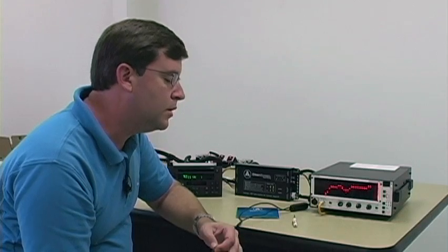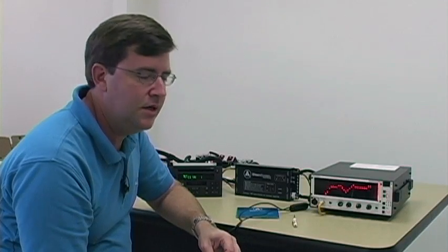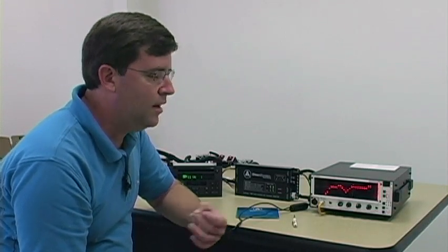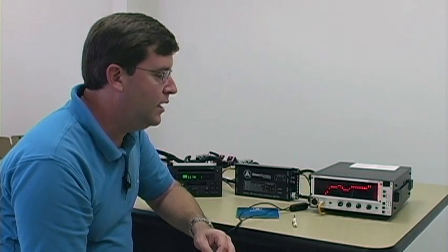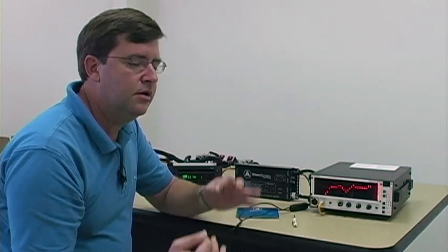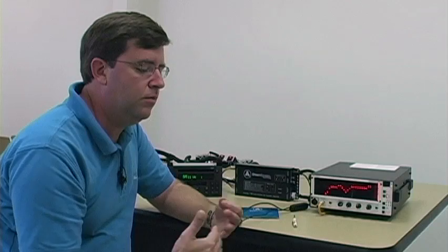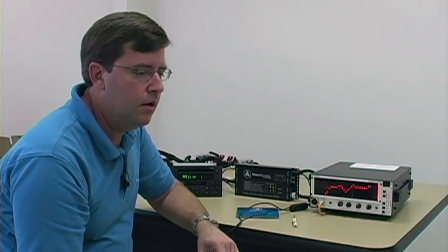There are several ways to do summing of signals. Probably the crudest way to do it is with line output converters, which we commonly refer to as LOCs. LOCs are passive devices that use little transformers, and they're inherently lossy by design, and they degrade frequency response further. And they have a very weak ability to level match signals that are of a different level. They can be used in a pinch in many situations, but it's really not the cleanest approach. Another way to do it is with an active preamp that has the ability to sum its outputs because the inputs and outputs are isolated.